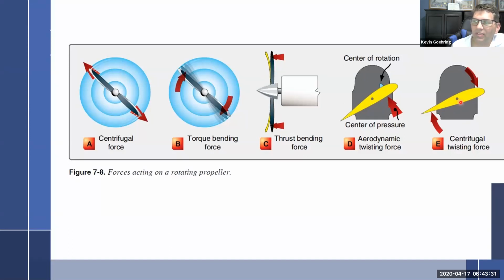When you swing something around, this mass wants to rotate, actually wants to rotate this way and be in line with everything. It doesn't want to come back out. So this one wants to bring it towards feather. This would be feather up here. And this wants to bring it all the way to a flat pitch, completely flat. And that's where it wants to be.